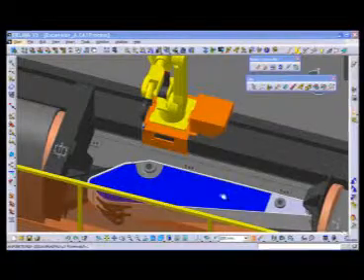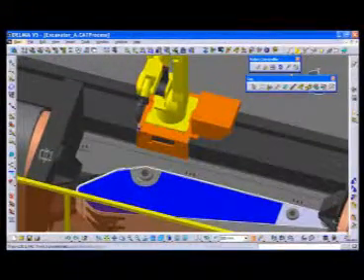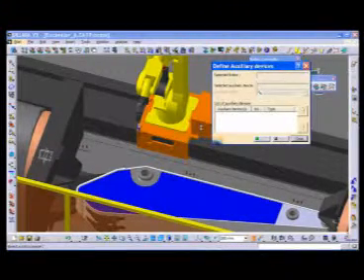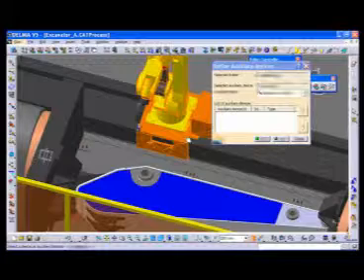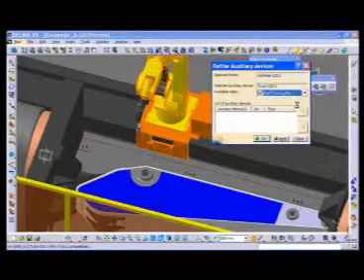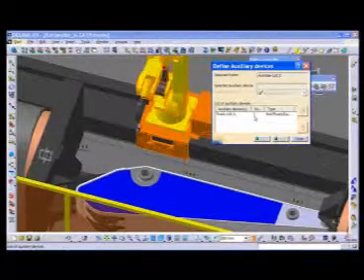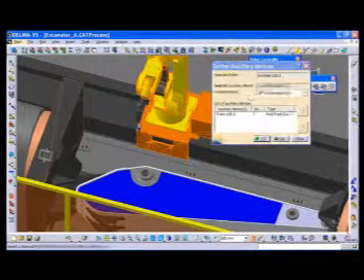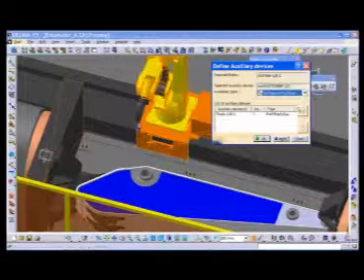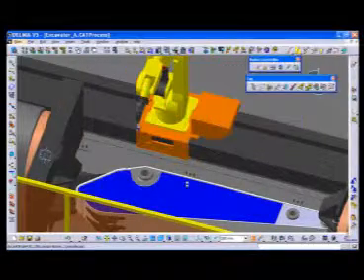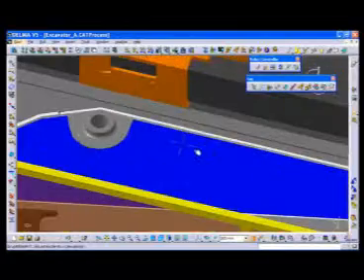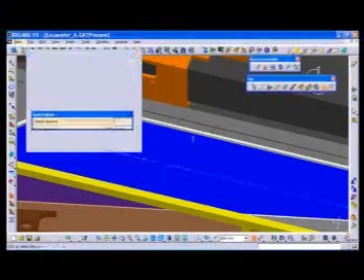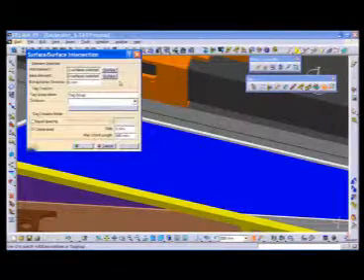So using the software to attach the robot, we first pick the robot, then the gantry. Now we have to define where the auxiliary device is attached. An auxiliary device could be located at the base of the robot, like the gantry, on the floor, like the part positioner, or it could be at the end of the robot arm, like a weld gun. Combining these devices allows each axis to be considered as part of the robot. So all the positional data of the robot and the aux axis can be communicated to the robot on the floor through offline programming. Now the work cell is ready to start creating robot paths.